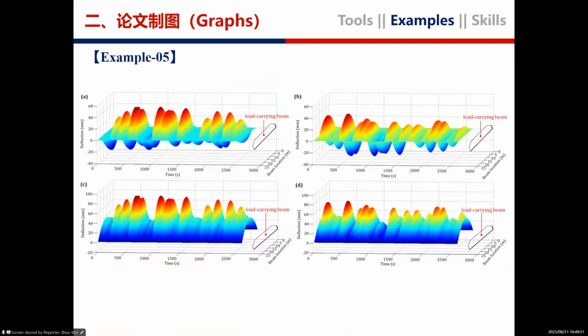In this work, we finally use our theoretical model to reconstruct the deflection curve face based on the detected dynamic strain. So this three-dimensional deflection can be given in MATLAB programming by using the surf function with contour options. And we intentionally stretch the range size along the time axis to make the contour plot look reasonable. Then we get the ultimate graph in PowerPoint with notes of the load carrying beam beside it. Okay.